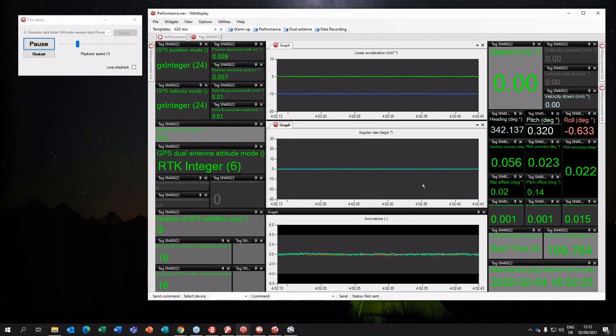So a 1 to 3 minute warm-up perhaps if you're using the XNAV 650, and you would use this. Looking at these accuracies here, you might use these to gauge when the warm-up is complete. For example, this data is for a Survey Plus, and you can look on the data sheet for the specification. It's 1 centimeter accurate, and you can see the device is reporting about 8 millimeters north accuracy, 6 millimeters east accuracy.